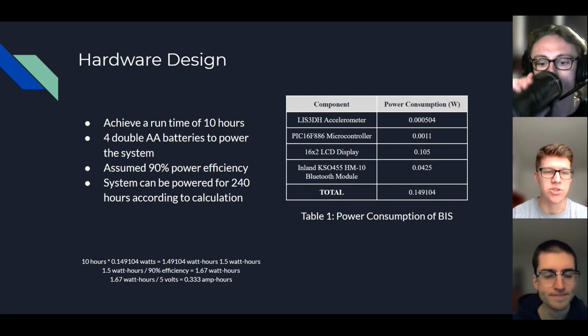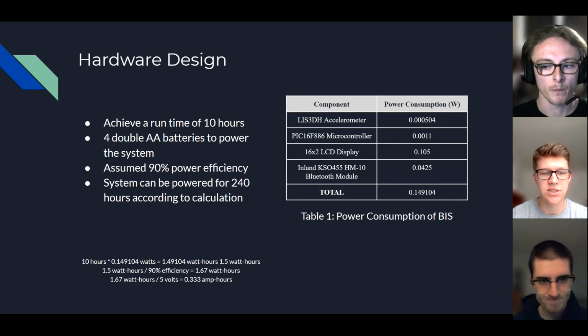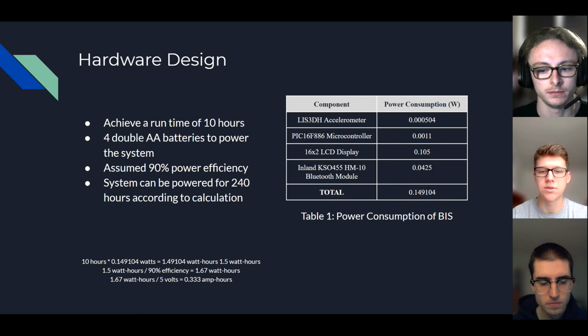And then we assumed 90% power efficiency, and we calculated that when using 4 AA batteries to power the system, we'd be able to power the system for 240 hours.